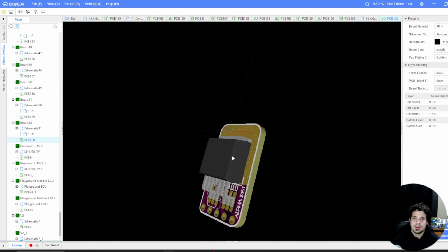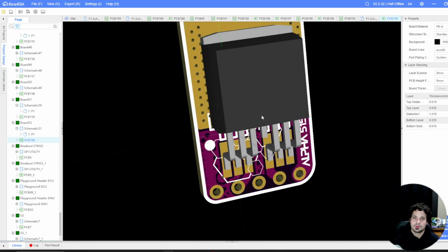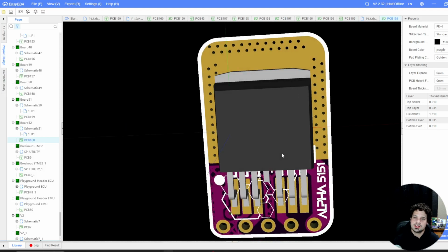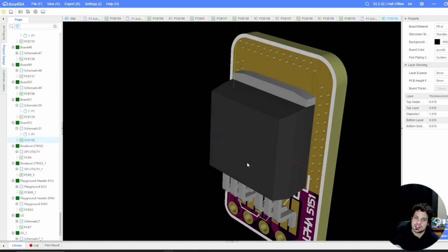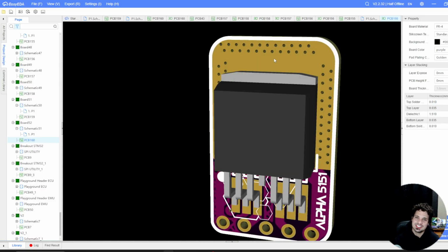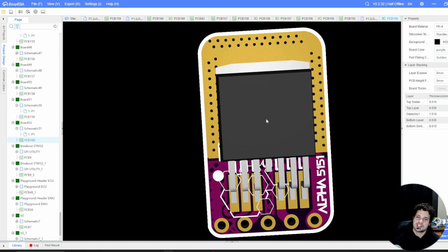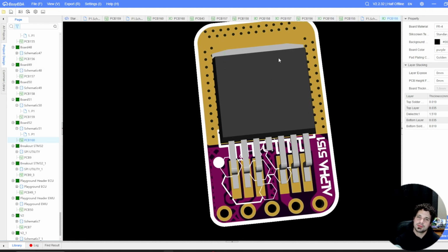So the beauty of using my replacement here is that it actually replaces the 5151 not only in relative footprint size, but in excessive cooling design. So this is designed to release tons of heat so that the IC lasts a long time. And on top of that, it is an inexpensive design. This allows you to use an IC that is approximately $2 to $3. The PCBs are pretty much cents on the dollar, especially when you panelize them.